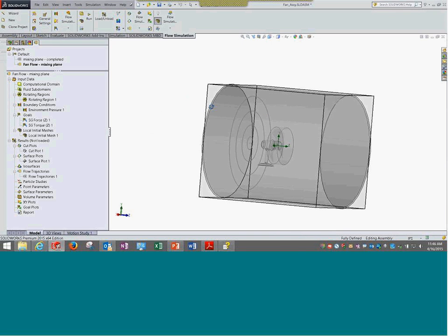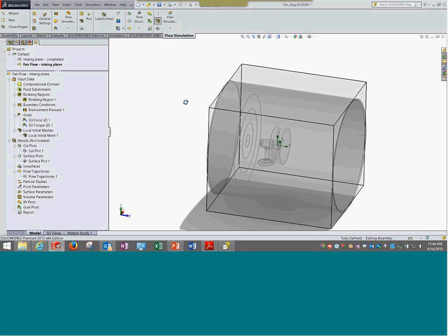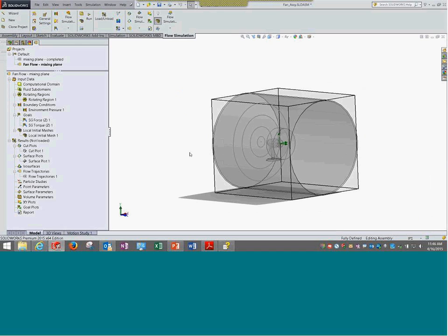So the new or different things: you activate the rotation region in the general settings of the wizard. Now ensure that you have refined mesh at appropriate locations. If you are curious, you can run a solution without refining the mesh, and later you can see the difference when you use the refined mesh, and how accurate it will be. In the end, I have seen it does not capture the rotation by itself if the mesh is not good.